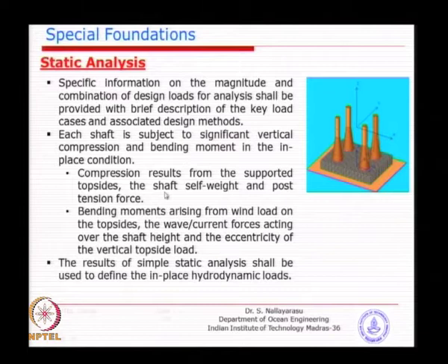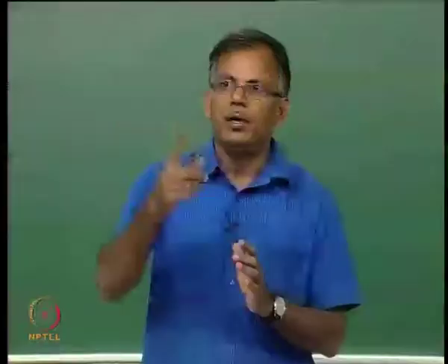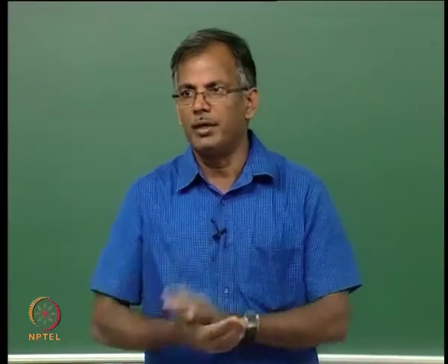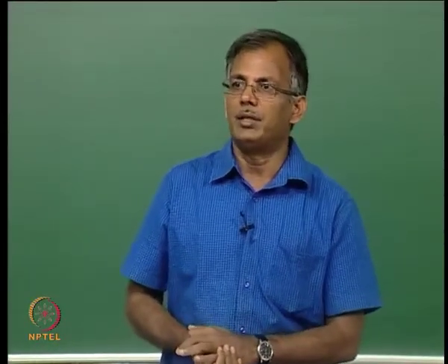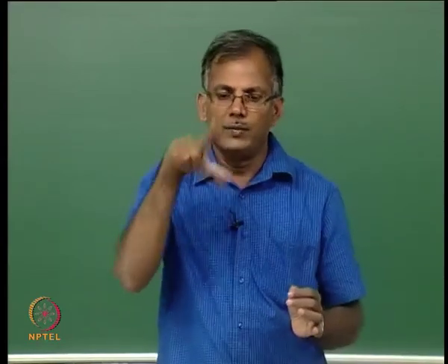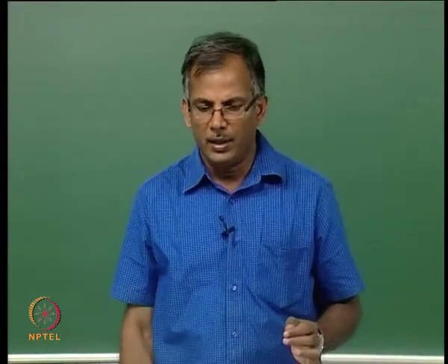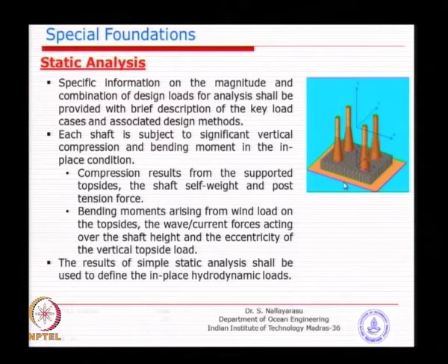You can simplify the nonlinear spring into a linear spring, which we accept as a methodology for this type of structures. That means when you develop a TZ curve, which you already have an idea of how to do, you need to linearize it and give that spring here, and basically that will be the interaction between the soil and structure.